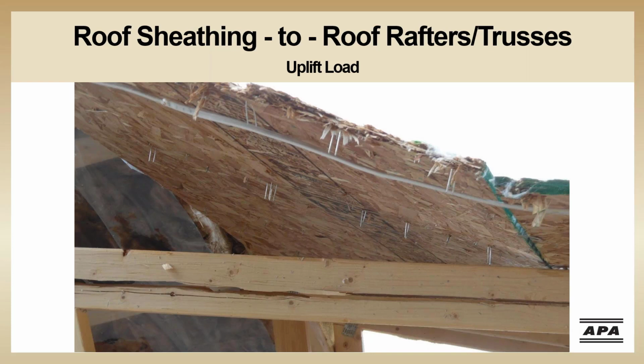Another reason why the loss of roof panels is so common during high wind events is that staples are often installed with the legs perpendicular to the framing member, as seen here. Installing the staples perpendicular makes it difficult to ensure that both legs of the staple engage in the framing member. When the staple is installed parallel, it is easier to ensure that both legs engage.